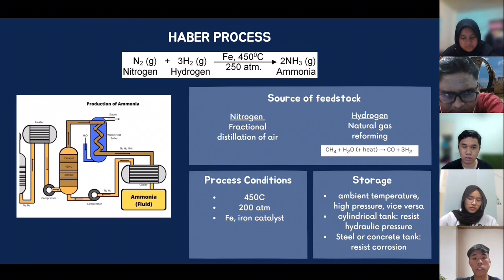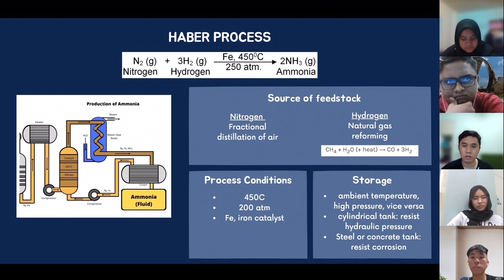Liquid ammonia is stored either at ambient temperature under high pressure or at negative 33 degrees Celsius under atmospheric pressure. Out of all the dimensions, a vertical cylindrical tank is the best shape and easier to handle for an ammonia storage tank. Due to the benefits of conserving steel, lowering floor space, improving operation management, and minimizing storage tank attachments and pipeline length, huge storage tanks are commonly used to store various petrochemical products.